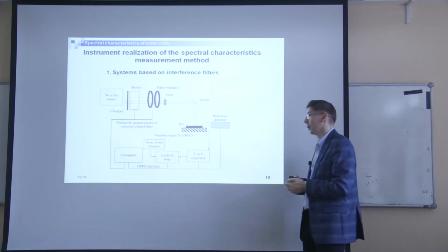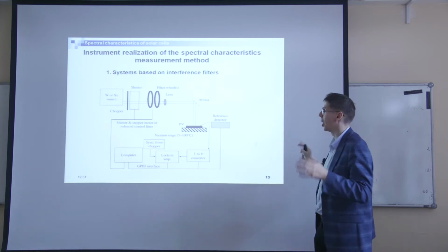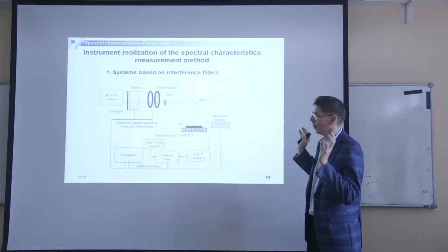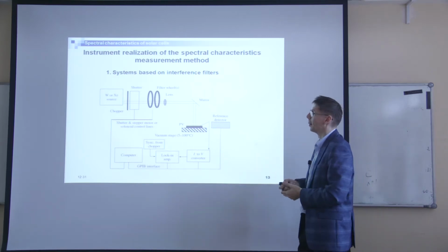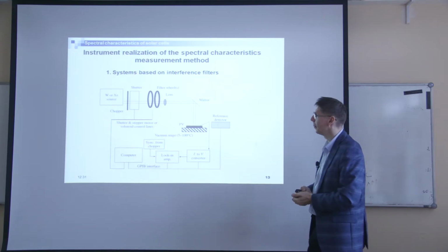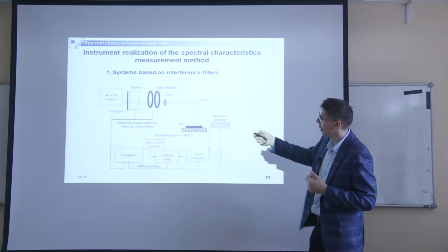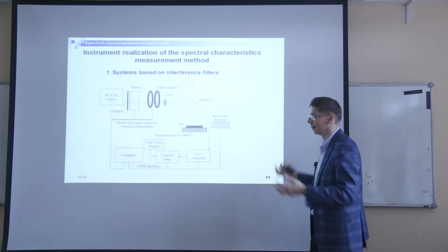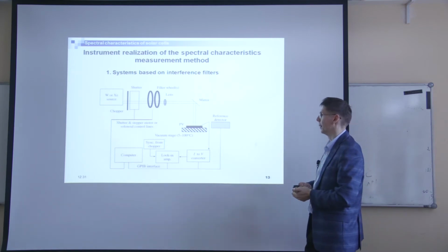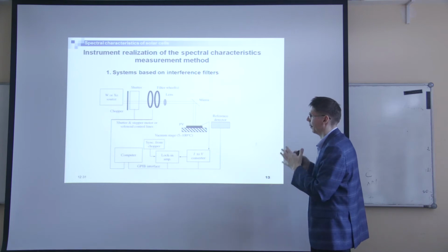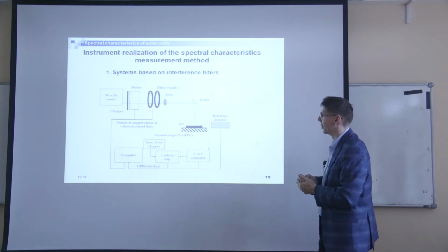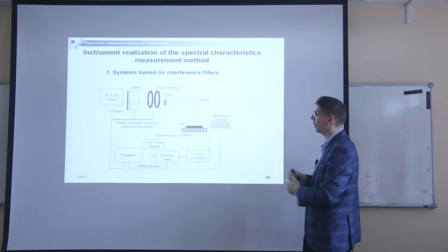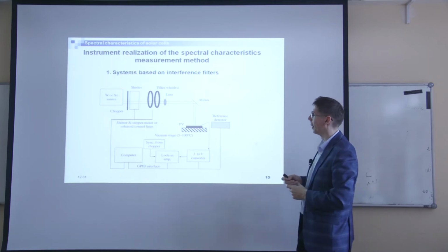If you want to make measurements of some module or some large area, then you can use some source of light. There could be different sources of light. It depends on your spectral region. And using the appropriate filter, you can select the wavelength, or actually the region of wavelengths, because a filter always has some bandpass.